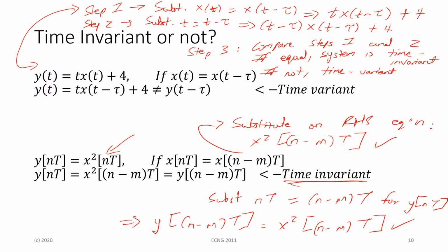In particular, the Laplace transform goes hand in hand with the initial and final value theorem to evaluate the transient response and the steady state response of systems. And poles and zeros will determine whether a system is stable or not. So we're looking at those as well.